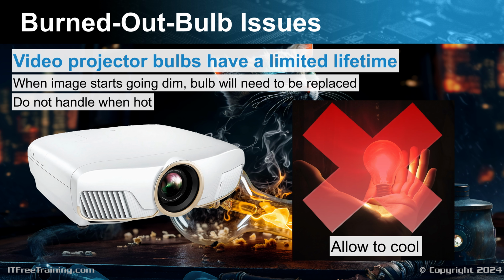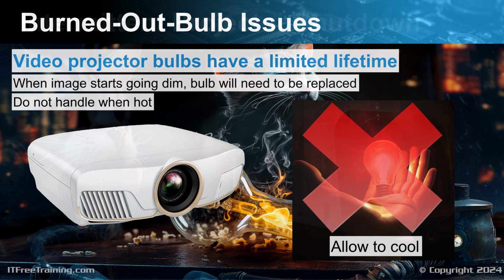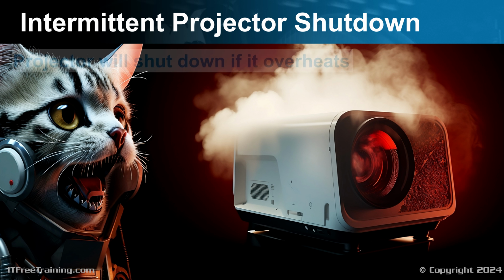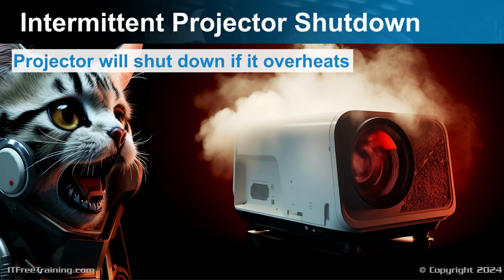If you handle it when it's hot, the bulb will be a lot more fragile, making it much more likely to break. Even if you're replacing it, you don't want the bulb to break while you're trying to remove it and glass to fall inside the projector. If you're having trouble with your projector shutting down, it's most likely overheating. The projector will shut down if it overheats.